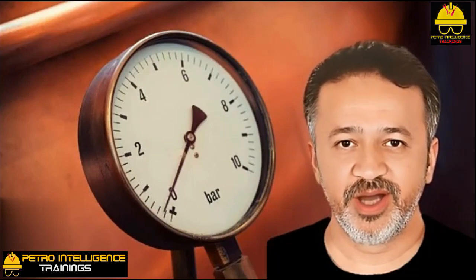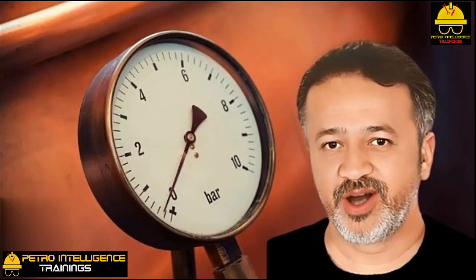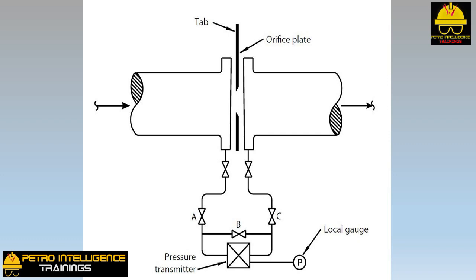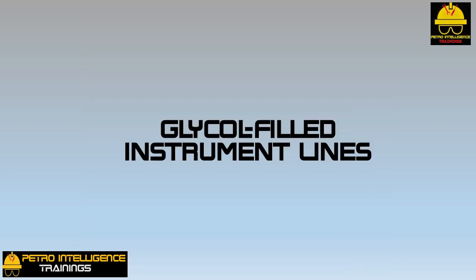More commonly, we have rotameters, which measure how far a ball or float is lifted in a vertical tube by the velocity of the liquid. But regardless of their relative merits, perhaps simply for historical reasons, the vast majority of flows in most process plants are measured with the orifice plate flowmeter as shown in this picture.